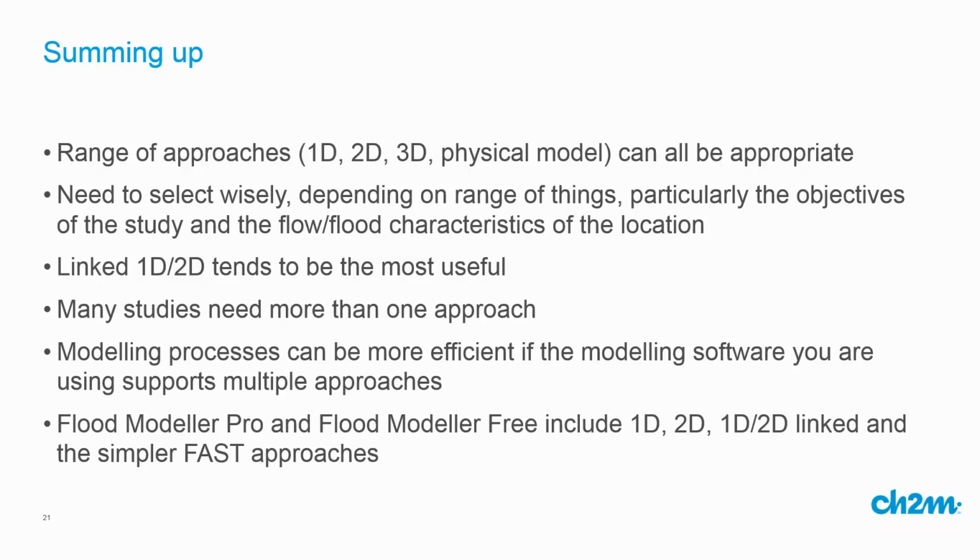As I keep on saying, this linked 1D, 2D tends to be the most used and most useful approach at the moment. Although in many studies you'll want to use more than one approach. So you may have a lumped hydrological approach upstream with some flow routing down to a point where we've got a 1D model with extended sections moving down the upper parts of the catchment that we're modelling hydraulically, and then we may get to the communities in the urban areas, and then we may move to 2D on the floodplain, but 1D in the channel for those things.